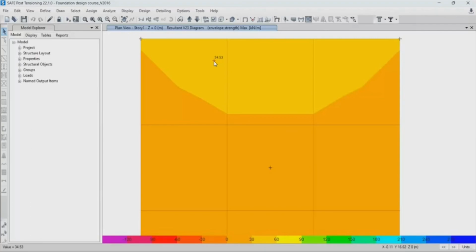The forces are going to be calculated per unit width, right? Per unit width, and the resulting steel demand is going to be in millimeter square per meter, like per meter width. We are going to get the required steel demand. Okay, so this is for the finite element method.